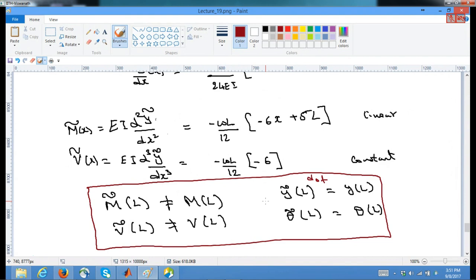If you have more nodes, that is with h convergence, with more and more elements, the piecewise solution will look closer to the exact solution. However, the forces or the stresses are not exact at the degrees of freedom. At a later point in chapter 4, I will show that the stresses are exact at something called Gauss points, which I haven't introduced at this point.